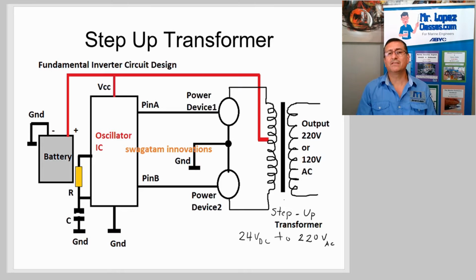I have an example of a step-up transformer, an electronic step-up transformer. Do you remember in our previous class the explanation about the inverters? I explained that depending on how you configure the batteries is the output of the inverter. If I configure the batteries in 12 volts DC, in the output, probably I have 120 AC, because internally in the circuit board of the inverter, you have a step-up transformer. If you configure the batteries in 24 volts, in the output, probably you have 220 to 240 AC.